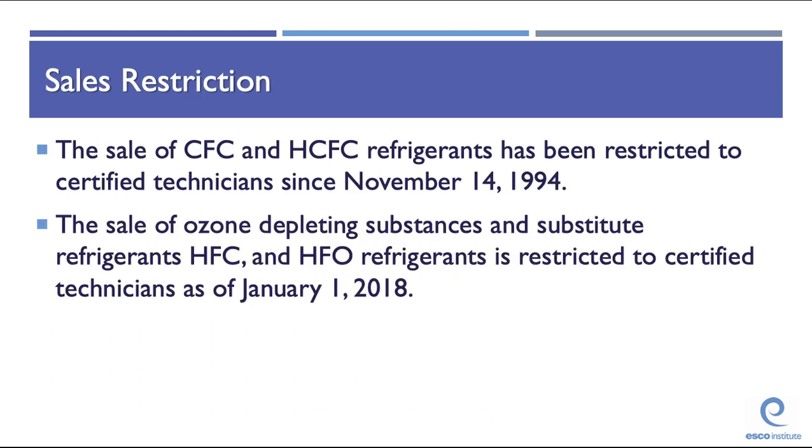The sale of CFC, HCFC refrigerants has been restricted to certified technicians since November 14, 1994. The sale of ozone-depleting substances and substitute refrigerants such as HFC and HFO refrigerants is restricted to certified technicians as of January 1, 2018. Only technicians who are certified under Section 609 of the Clean Air Act, Motor Vehicle Air Conditioning, are allowed to purchase refrigerants in containers smaller than 20 pounds.